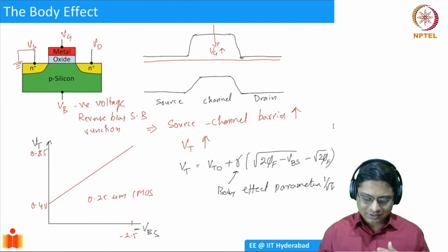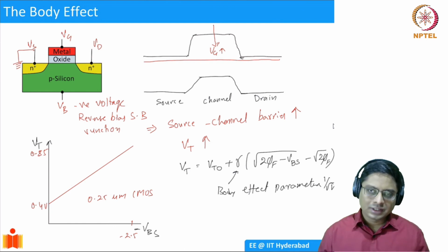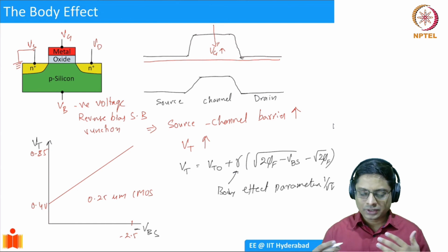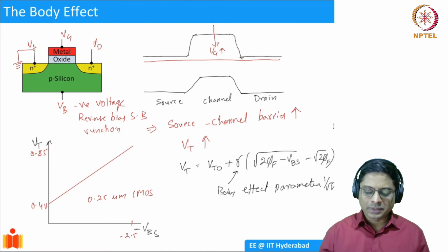So to summarize, the main tools that we have as a user are that we can change the drain voltage, gate voltage, or the bulk voltage, all of them with respect to the source. If you have a body effect, well, the VT changes. If the body voltage was 0, then you have VT naught, which is the default VT, or it can change depending on the body effect.